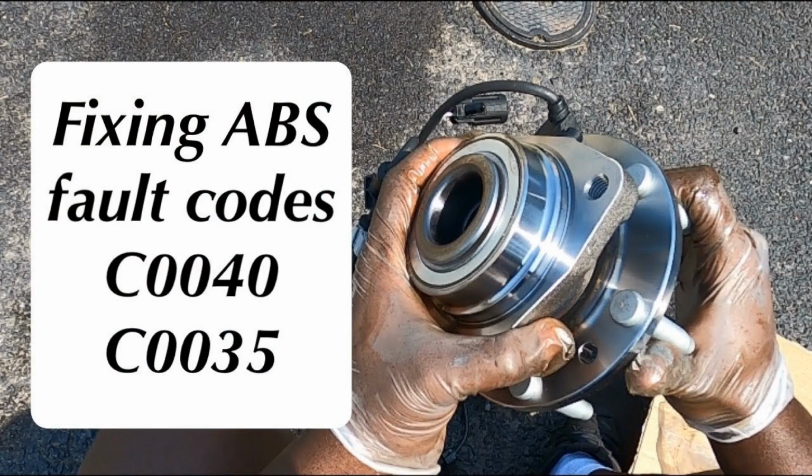Wheel speed sensors are responsible for providing wheel speed information to the electronic modules. These modules use this information to prevent wheel lock-up and ensure the vehicle's stability functions. Typically, there are four sensors, one at each wheel, although some earlier ABS systems on rear-wheel drive vehicles may measure rear axle speed or transmission output shaft speed. ABS-equipped cars generally have four sensors, and vehicle dynamics systems have one sensor at each wheel.